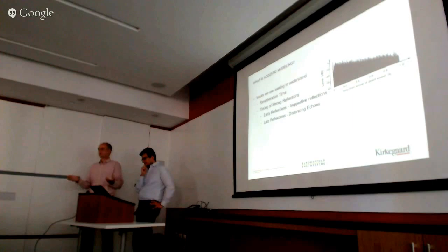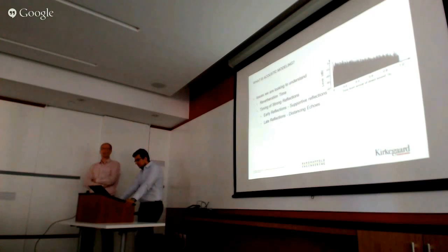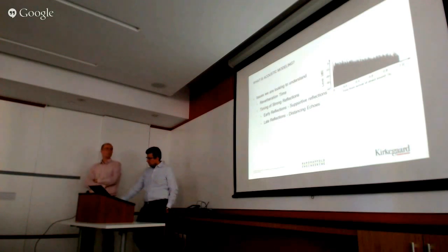So I'm sure you've heard of reverberation time, which is the longer term duration of sound, and how long it bounces around between reflective surfaces. But again, the timing of those other reflections really is a crucial part of how a room sounds, and also largely what we're looking to design for when we're thinking of geometric models. So those are the first two things that we look to understand about any room that we're designing.